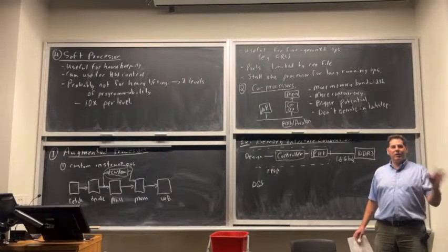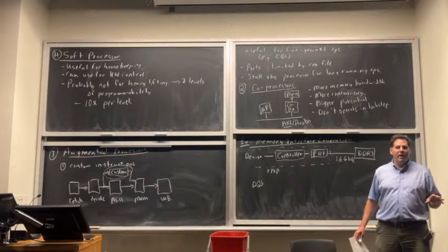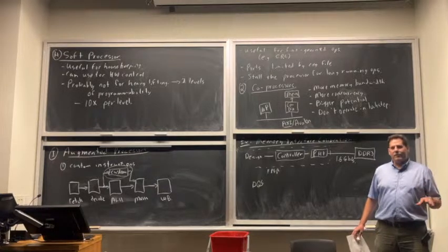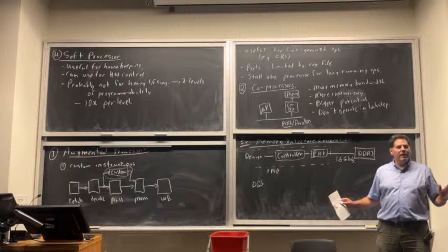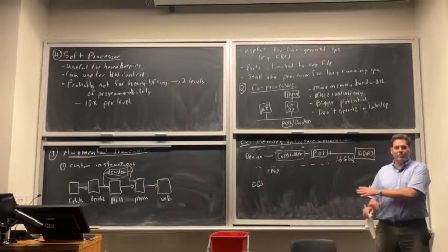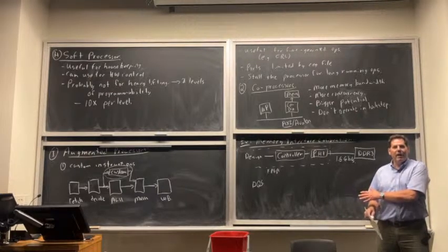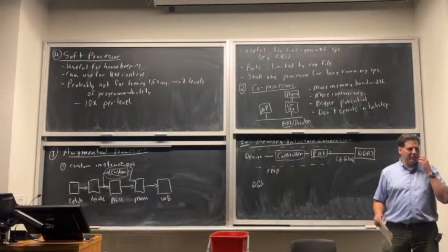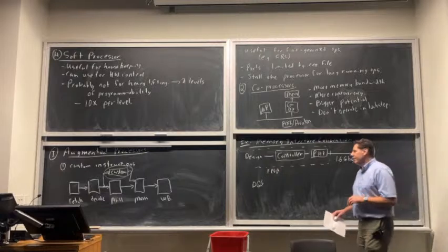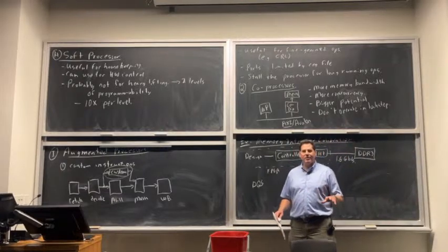At really low frequencies, you can basically use a single clock on the motherboard. All the chips have the same clock. You send data on that clock. The other chip receives it at the next edge. You can only do that at very low speeds. So these are very simple interfaces that don't transmit very much. It's really basic stuff.